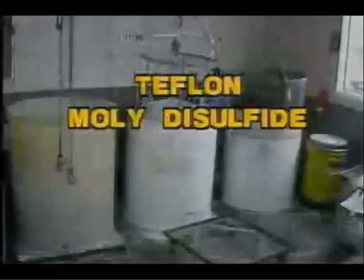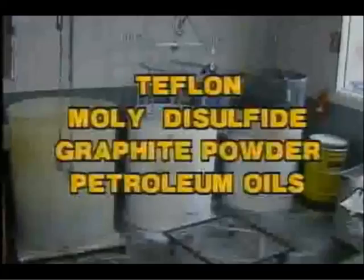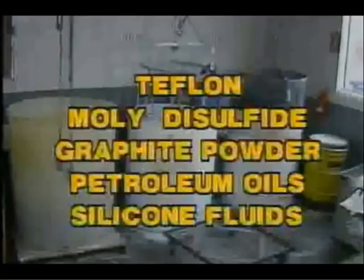There are two categories of essential lubricants used in mechanical packings. Break-in lubricants provide protection against excessive heat buildup until the packing becomes pliable and seated. Built-in lubricants serve as blocking agents to decrease packing porosity and provide some resiliency. Some common lubricants used for these purposes are Teflon suspensoid, molybdenum disulfide, graphite powder, petroleum oils, and silicone fluids.